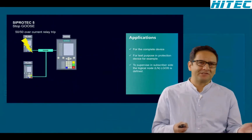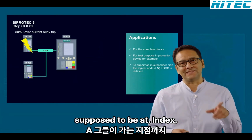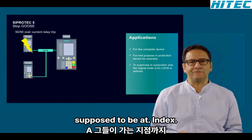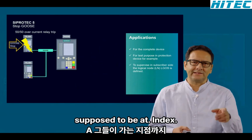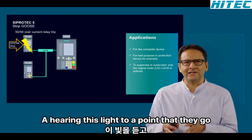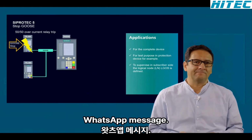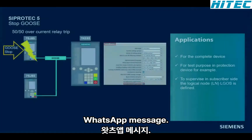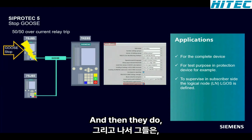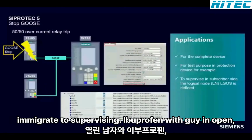As you can stop the analog signals coming via sample values stream, it's also possible to stop the digital signals that are coming via GOOSE, also via 61850. In the example here in the slide, the GOOSE stop signal is generated to avoid that, in case of testing of the overcurrent protection, the GOOSE signal is going to start the fault recorder 7KE85. Also, to supervise the GOOSE message, it is possible to enable GOOSE supervision in DIGSI under the settings of the device. And then the logical node LGOS will be created to supervise them.